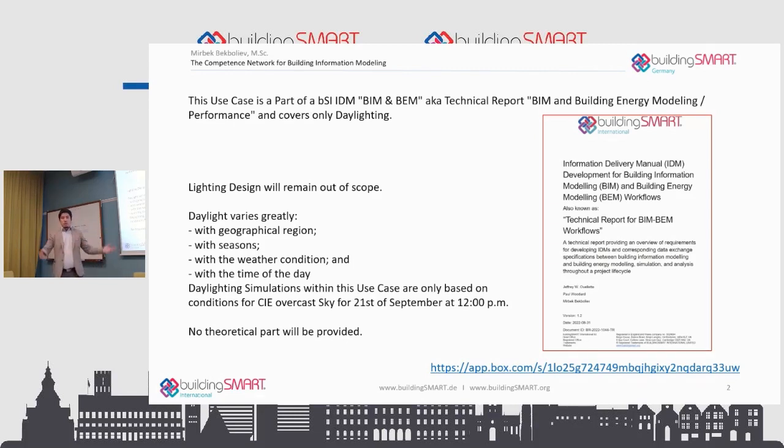It means on the south facade, you may create bigger windows. If it's a heating-targeted area, like in Norway, I would say, not in Dubai somewhere, you had better reduce windows on the south facade. But at the same time, you need to think about solar shading, because overheating is always there. Then you will not have to use air conditioning, which would be another load for your energy system.